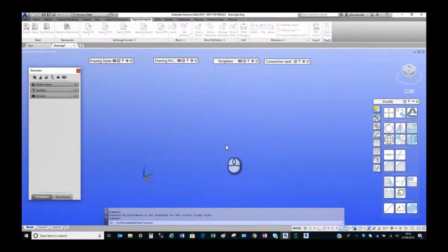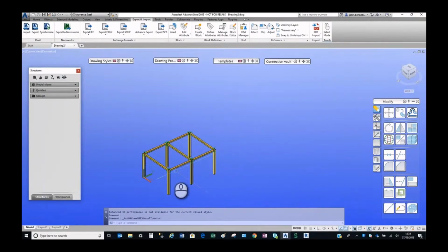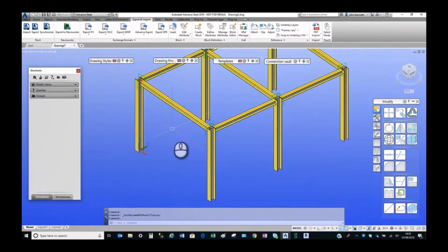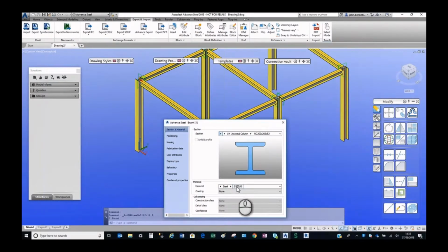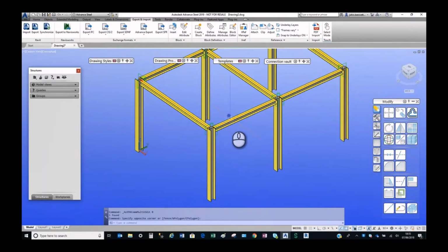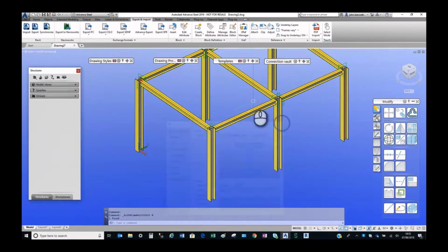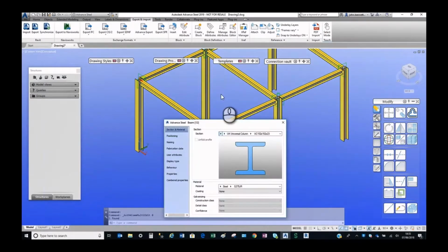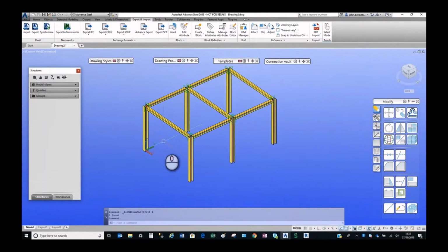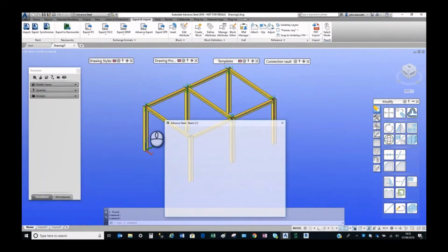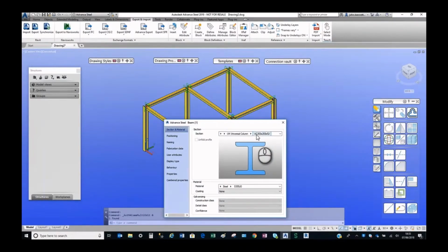So I just select the file through the import ribbon and the import button, and you can see that it's brought the sections in. We've just got primary sections at the moment, and if I click on one of those, we can see that the materials have come across. I'm going to click on a different one just to show you that it brought the beam size and the material across. It's slightly different materials there. So all this is coming from Revit into Advanced Steel via the mechanism of the approved family. And this is the primary transfer mechanism, without any joints. This is what happens.